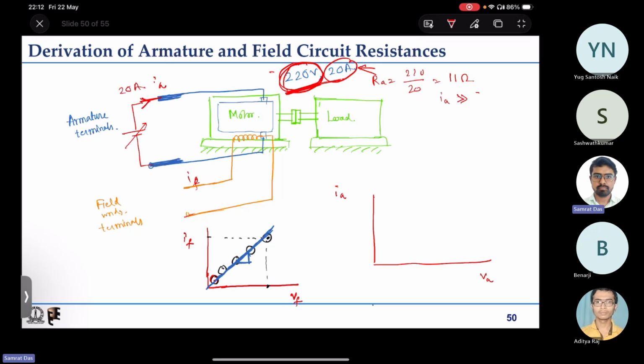First we make 20 ampere current flow for some time so that the winding becomes hot, because current flow and temperature are not simultaneous quantities; you need some time for the winding to get hot, say 1 to 2 minutes, 5 minutes, whatever small amount of time.